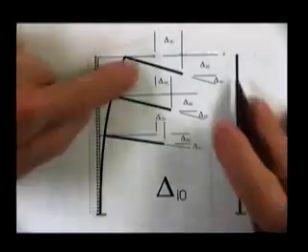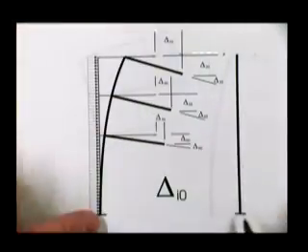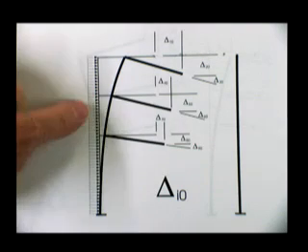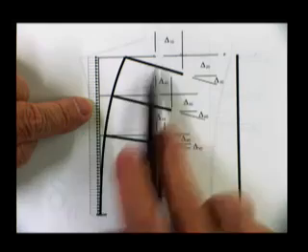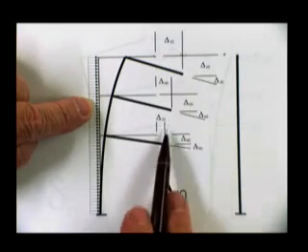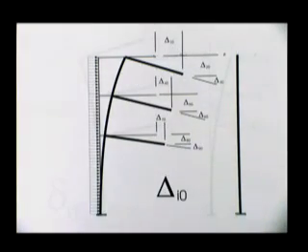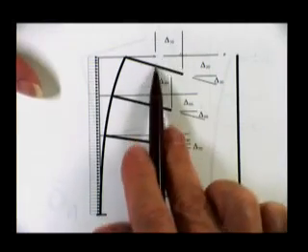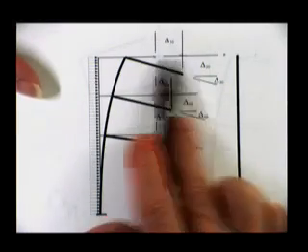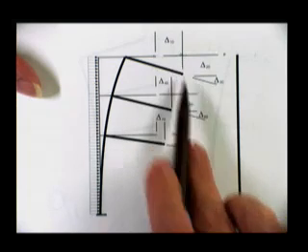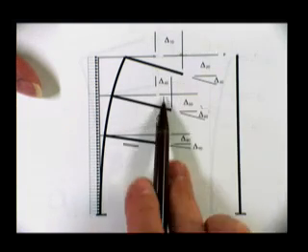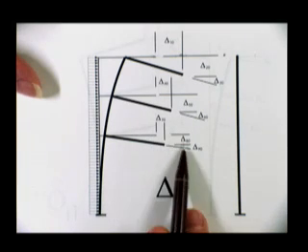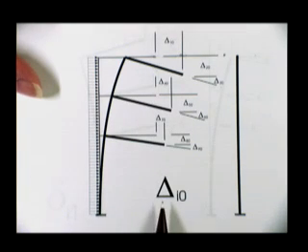Here are the deflected shapes due to the real load, and then label the deflections. Well, it's due to the real load, so they all have subscript 0 on the tail end. And this is the number 1 direction, this is the number 2 direction, and the rotation of this piece here is the number 3 direction. And 4, 5, 6, and 7, 8, 9. And that's delta sub I0, where I goes from 1 to 9.